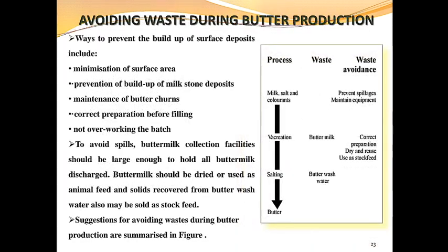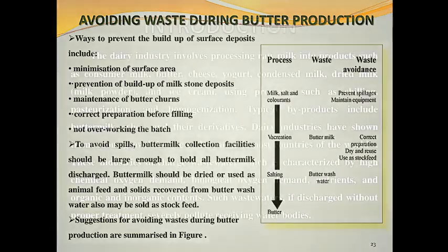Next, avoiding waste during butter production. The ways to prevent the buildup of surface deposits include minimization of surface area, prevention of buildup of milkstone deposits, maintenance of butter churns, correct preparation before filling, and not overworking the batch. The process converts milk and salt into butter, and the waste generated is buttermilk and butter wash water, along with some precautions.